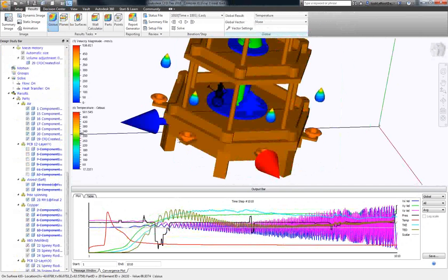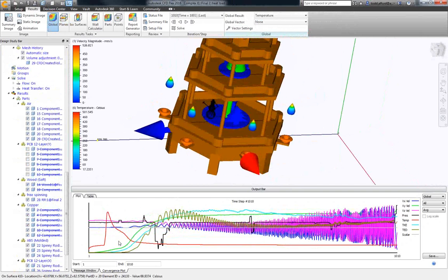But first off, the way that the physics work to drive the relatively odd shape for the temperature line, it's going to heat up, that's going to change the density, and then the air is going to move. So this is something that we very regularly see in a natural convection analysis. Now, this thing's diverging, right? Look, these lines are going up and down, and it's completely crazy. How could you trust that?